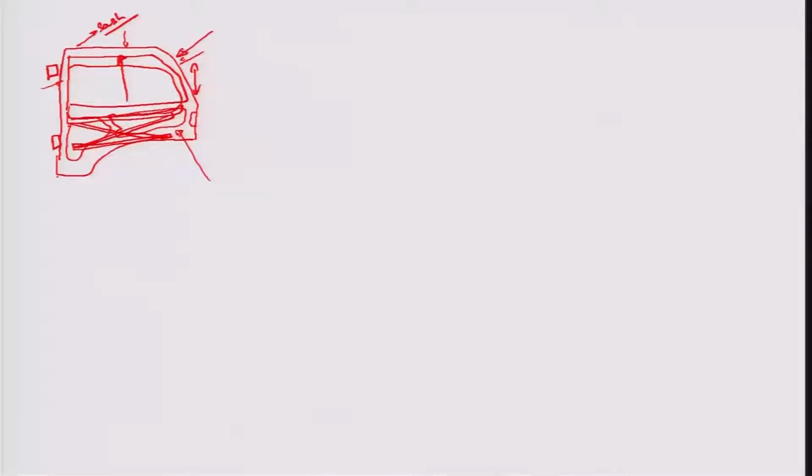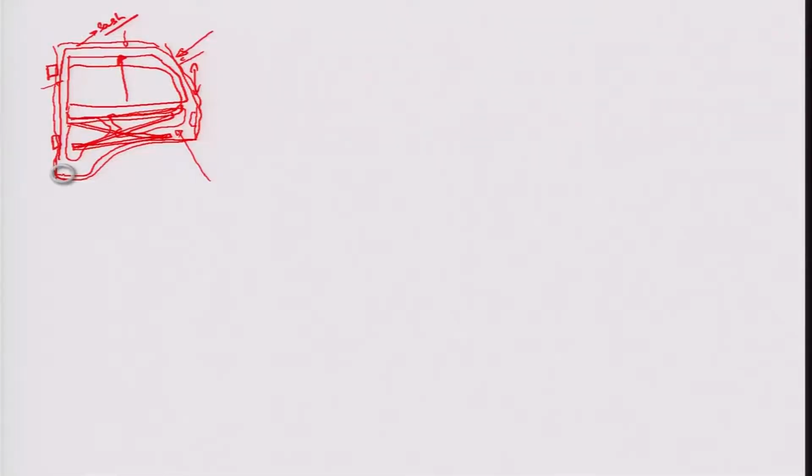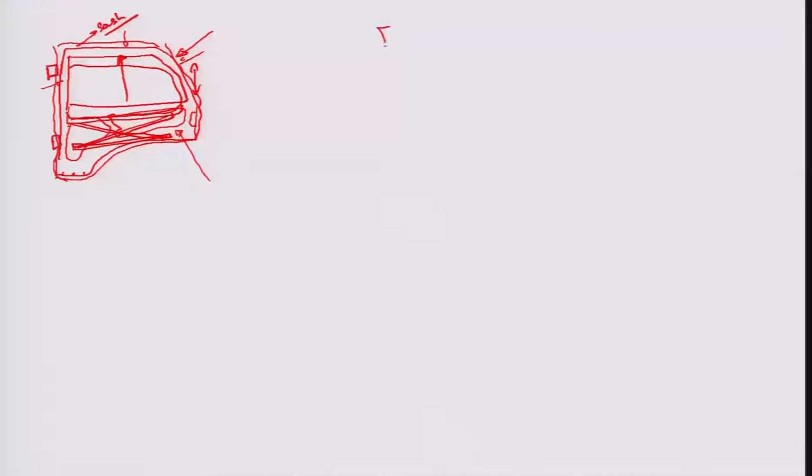because if we look at the door and if we look at the pressure that it creates with respect to the body in order to prevent the shower or other leakages coming out from the door, there is a weather strip, door weather strip, which is around this whole door, and it's basically a rubber cushion which actually press fits with the door on one side and the side body on another side. And this rubber cushion is actually fitted with some small holes which are there at different portions of the door inner and outer. So the inner and outer, the inner member being the ribbed member and the outer member being a continuous member, are hemmed together.